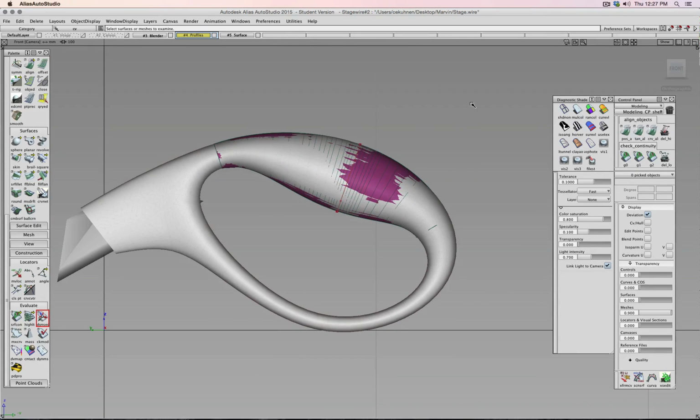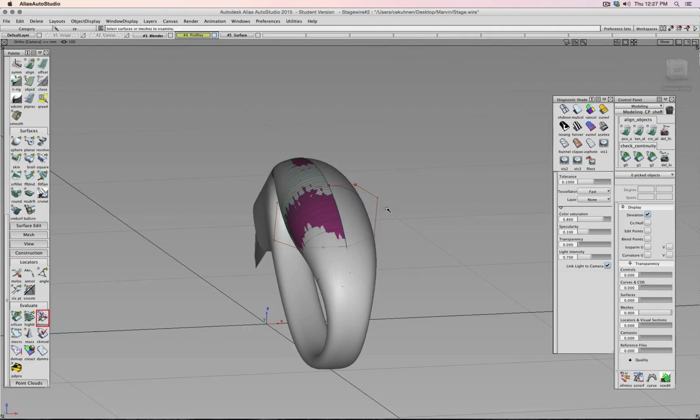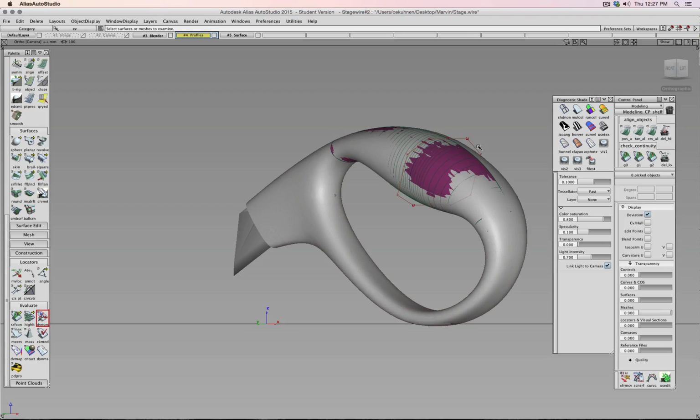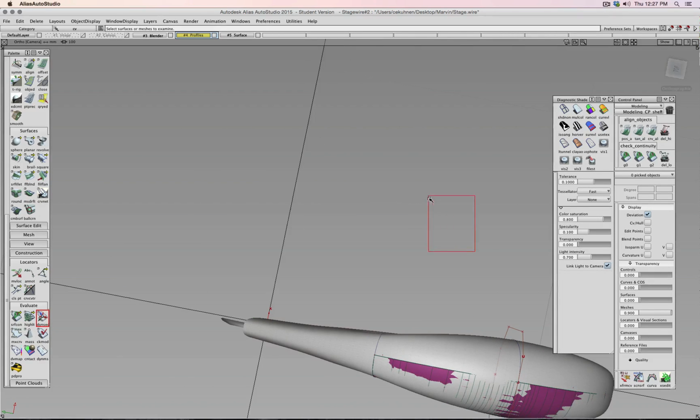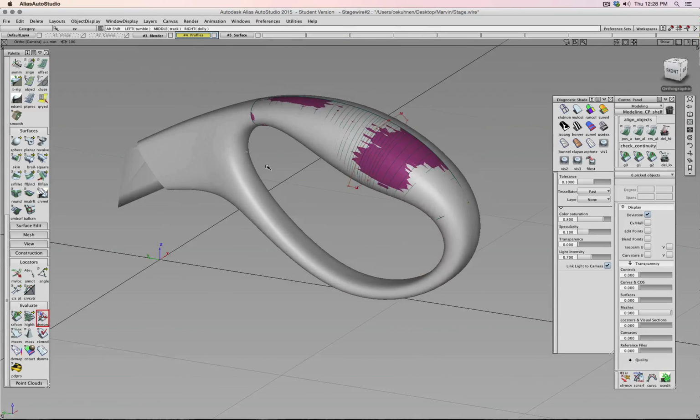So now my next task is, how can I, for example, work on this section and build this one out. So let me see. So this is, for example, now where stuff gets somewhat tricky. In Blender, when you work with sub-D, it's all like one rubbery fluid surface, so everything flows together. And in Alias, or with basically NURBS, you really have not only to plan on how from the side, for example, those surfaces flow, but also, for example, from this view, how along here you have the flow. So that's why I meant before it's easier to have a computer model to see as a representation, and then try to visualize the alias geometry you have to project into it.